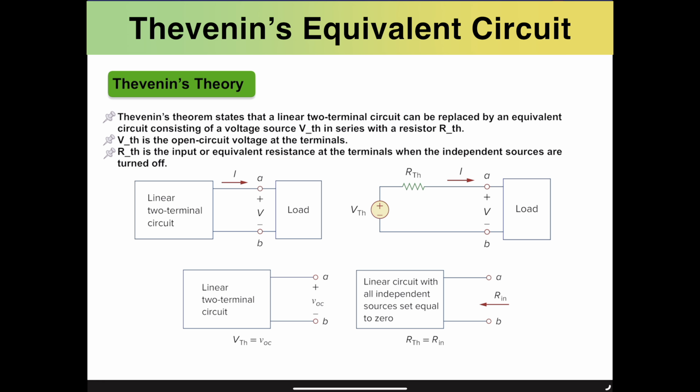So essentially, if you want to find the resistance seen from the A and B terminals, we would connect an arbitrary voltage source over here. We would call that, for instance, V. And we would need to find the current that is exiting that node with this polarity of the voltage source and this direction of the current.